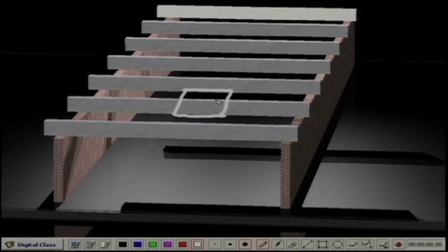This is the square, that means 1 meter by 1 meter, and like that it is going. When you talk about your beam, it should be per meter, the UDL per meter. So, whatever load we have got, that is 3.989 or about 4 kilonewton per square meter.